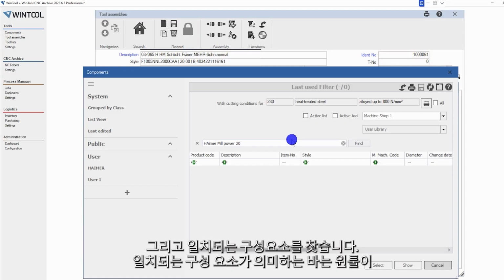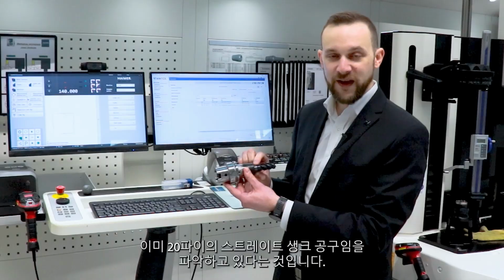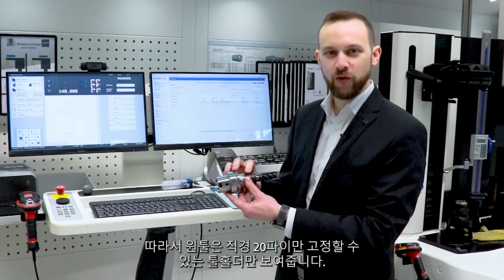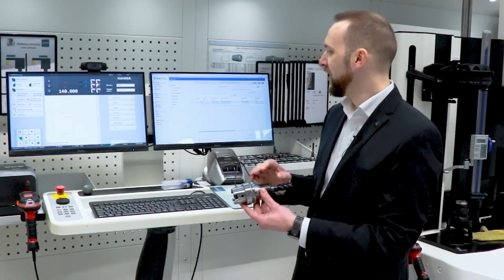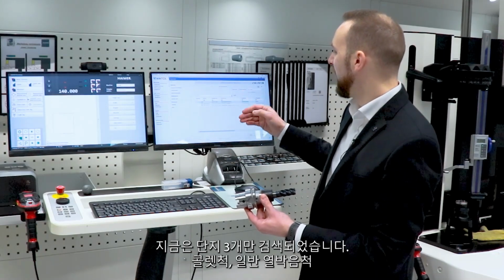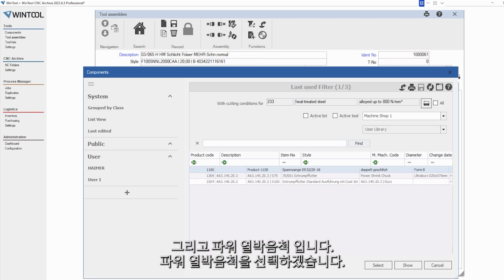And the matching component means that WinTool has the intelligence to know this is a straight shank, 20 millimeters in diameter, so please, WinTool, only show me the tool holders that can clamp 20 millimeters in diameter. And I have now only 3 results. That's a collet chuck, a standard shrink fit chuck, and the power shrink fit chuck. And I say, please take the power shrink chuck.